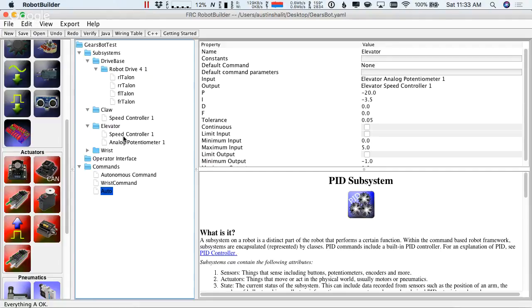As you turn the wheel, there's a little disc with a bunch of slots cut in it, and there's a light shining through the slots and a photocell on the other side, and it counts how many slots went by. That thing is not dependent on getting dirty. Well, if it gets dirty, it's bad, but they're encased in a package, so dirt doesn't get in them, and so they just work. But there are problems to solve with that because they're incremental rather than absolute. So with a pot, you always know where you are in the range of travel. But with an encoder, if you lose power, you don't know where you are anymore. You have to find some way to figure out where you are, usually using a limit switch or something.